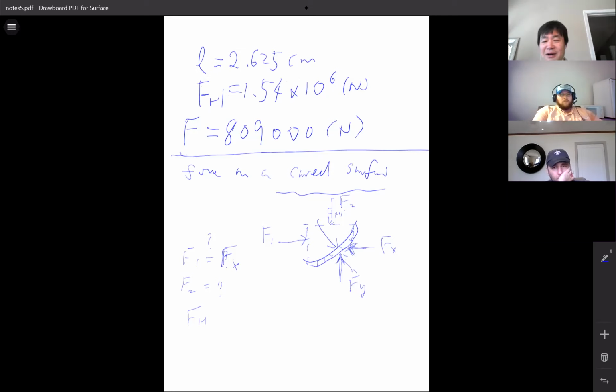It seems like my force is totally transmitted through the table to you. So it's the same. So this horizontal force F1 equals Fx. Great, so we find a relationship here. If we can find F1, then I should be able to find the x component of my hydrostatic force. They're equal. So what is F1? Anybody? Do you know how to find F1?